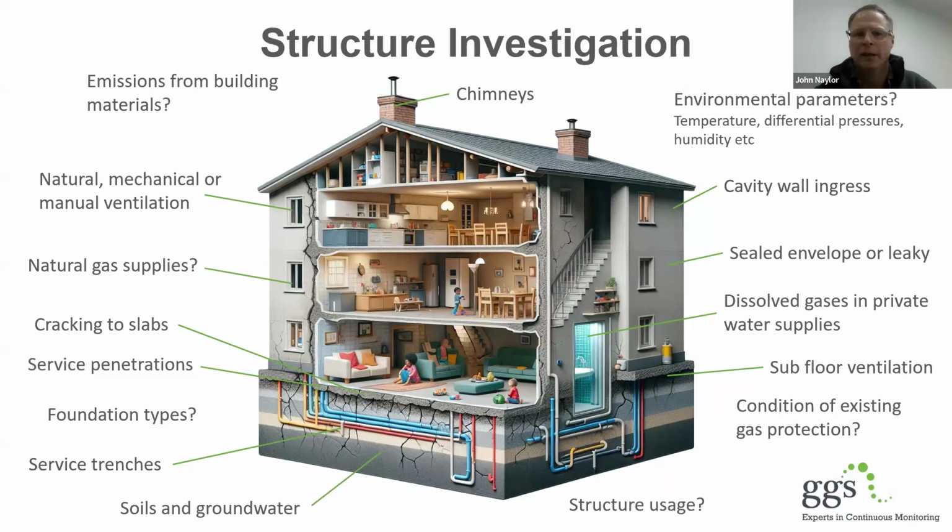Okay, what's the ventilation like? Is it good? Is it bad? Are they using it differently in summer and winter, which they probably are? And this is definitely what we see with radon. Are the chimneys? You're going to get stack effects within the property, all these kinds of things that you need to look at and think about.